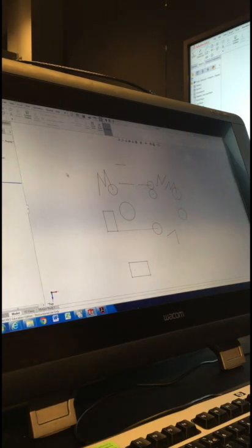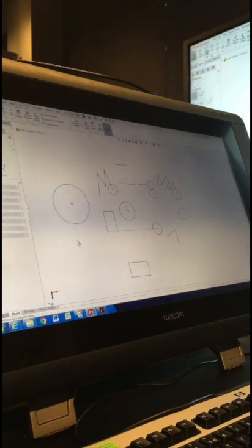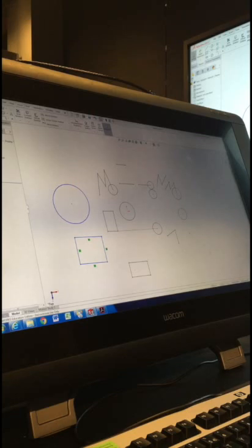If you start a new sketch by clicking, let's say, the top plane again, new sketch, you're drawing new lines, your new lines will be blue while those other lines are grey, all right, because you're in a new sketch. If you want to go back and edit the lines in the first sketch, you need to select that sketch that says sketch 1, or you need to double click on one of those lines. Okay, and that will get you editing that original sketch again.